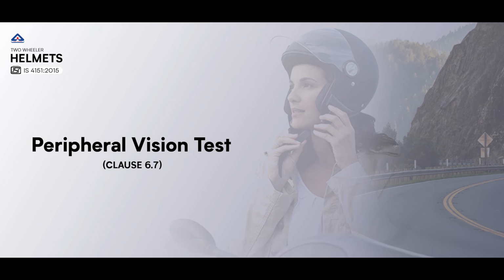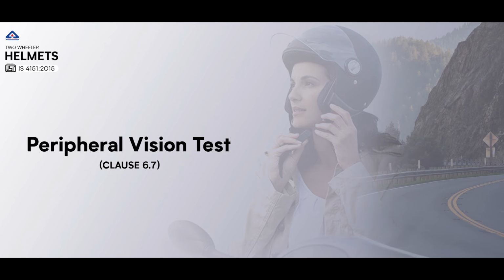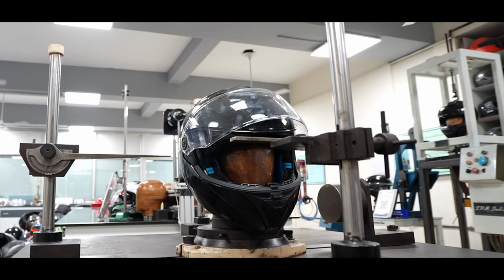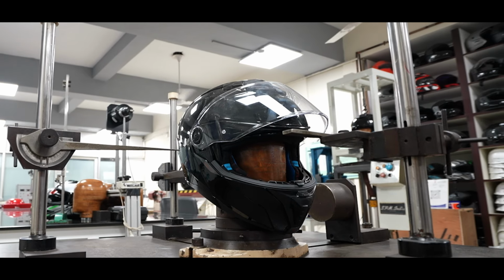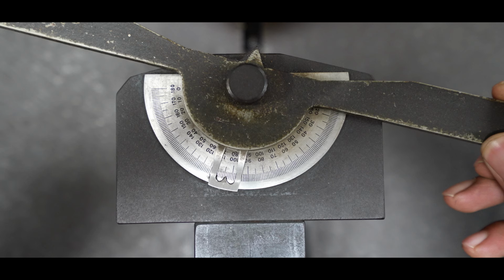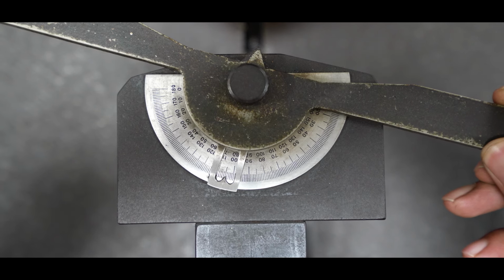Peripheral vision test, Clause 6.7. Peripheral vision is critical for rider awareness. Helmets must provide a clear horizontal field of at least 105 degrees on each side from the mid-sagittal plane.